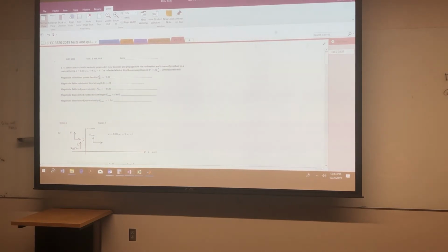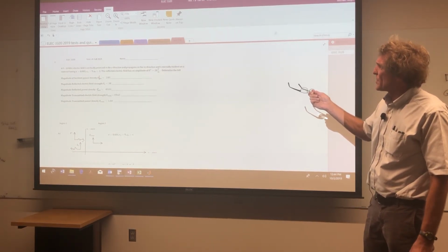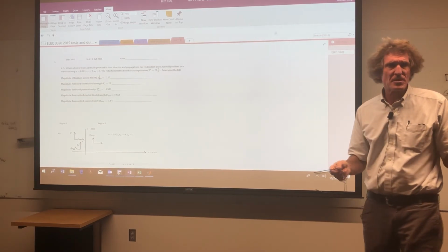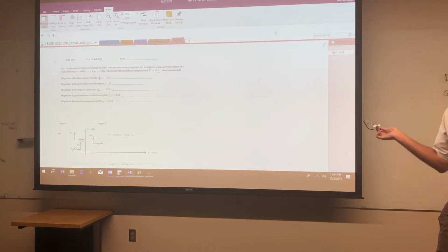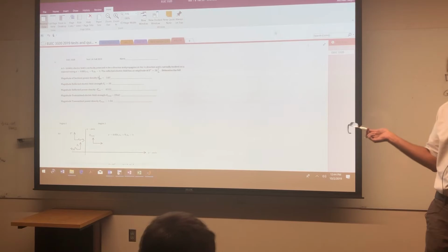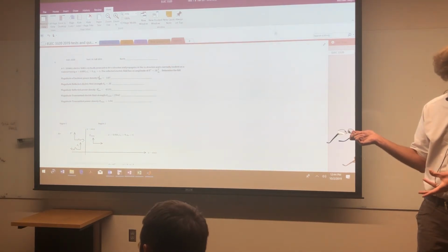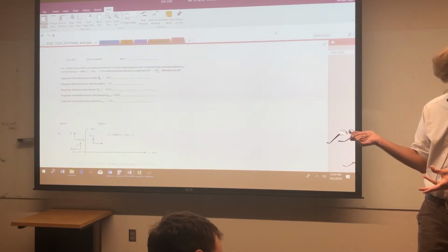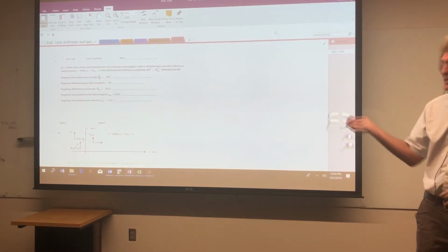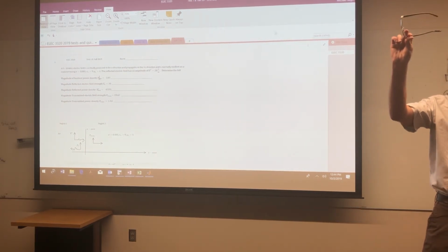This particular problem, like the first problem here, where you've got two media, what you're going to do is calculate eta 1 and eta 2 of the two different media. Have to get that. Then you get reflection coefficient, transmission coefficient. This is sequential, regardless of what's asked for. After you get that, if you want, you get transmitted, reflected, and incident field, right? You get all those things for E or H. Anything else you want, power and stuff like this, it's just using that, but it's methodical. It's going right down the thing.